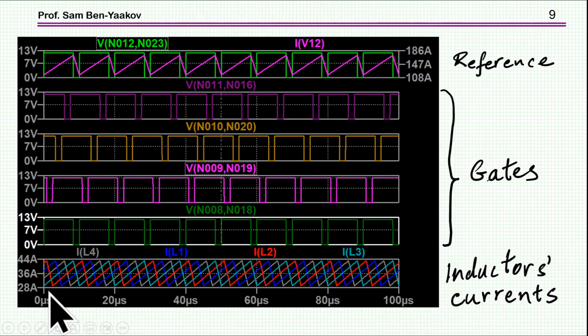And then we have the currents of the inductors very nicely interleaved. And this is why they are, of course, canceling partially each other, and therefore you get a total ripple which is lower. And in this case, they are the same height. This is because it's simulation, everything is the same. In the practical case, probably you'd like to have a sensing of the current and then have some mechanism control for current sharing. But here, with the simulation, you really don't have to do that.